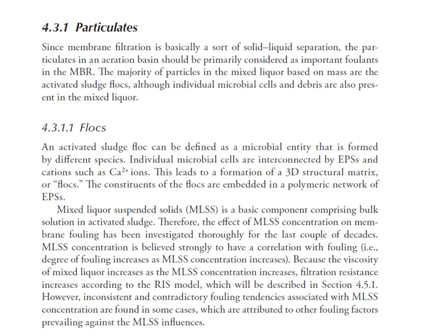Let's look at one by one. The particles. Since membrane filtration is basically a sort of solid-liquid separation, the particles should be primarily considered as important foulants in the MBR system. So that's why we normally see cake layer formation as a major fouling mechanism. And flocs are the main components, as I mentioned.